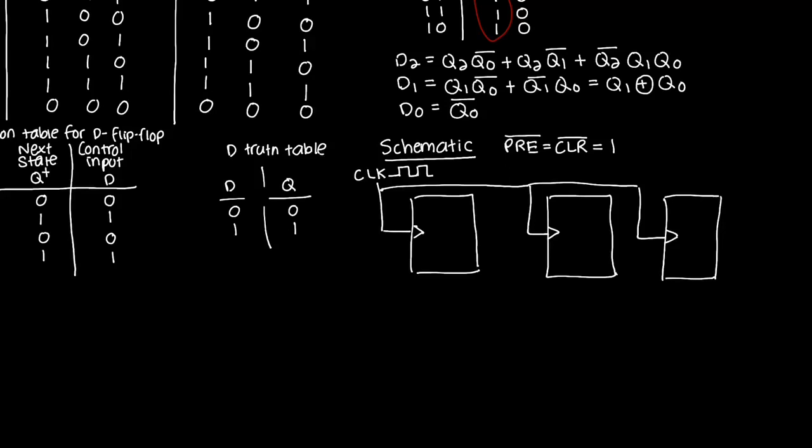And the next change that I'm going to make is, so one confusing thing about ripple counters was that even though when I write out a binary digit, my most significant bit is always on the left and my least significant bit is always on the right. That's just convention. But when I drew the schematic for my ripple counters, I put the flip-flop corresponding to the least significant bit all the way on the left, and the most significant bit was on the right. So I reversed the bit order visually in this schematic.